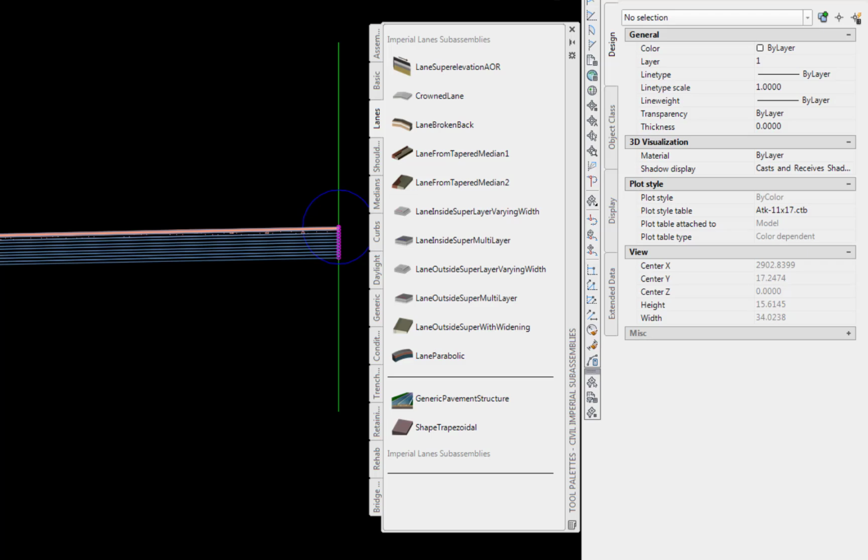The thickness of the pavement and base sections for a roadway are dependent upon the structural supporting characteristics of the subgrade soils and upon the design traffic loading. These are beyond the scope of this video. For this video, the road sections for the primary road consist of 4 inches of asphalt concrete pavement, to be constructed in 2 lifts, 16 inches of aggregate base, constructed in 2 lifts, and approximately 2 feet of undercut. The side roads and UAFS drive consist of 3 inches of asphalt concrete, constructed in 1 lift, 12 inches of aggregate base, constructed in 2 lifts, and approximately 1 foot of undercut.